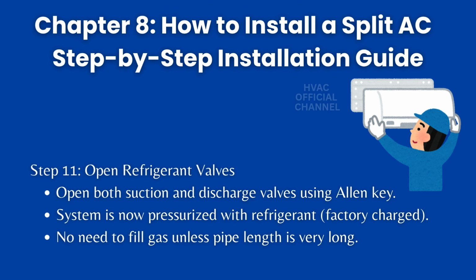Step 11. Open refrigerant valves. Open both suction and discharge valves using Allen key. System is now pressurized with refrigerant, factory charged. No need to fill gas unless pipe length is very long.